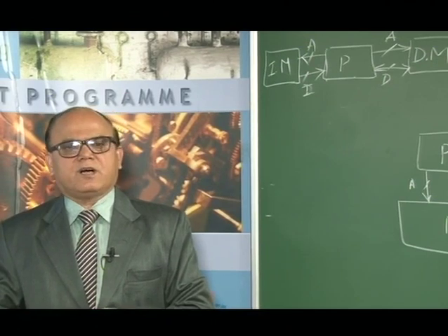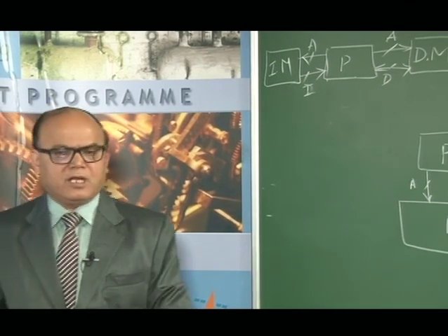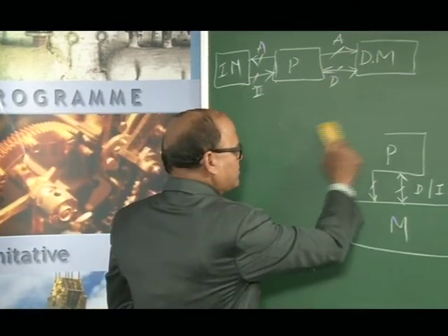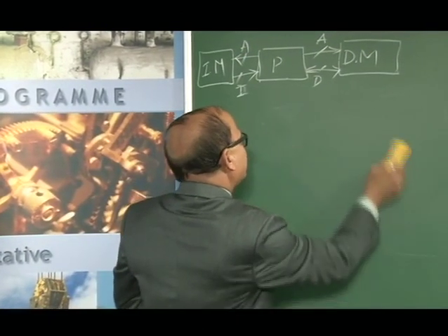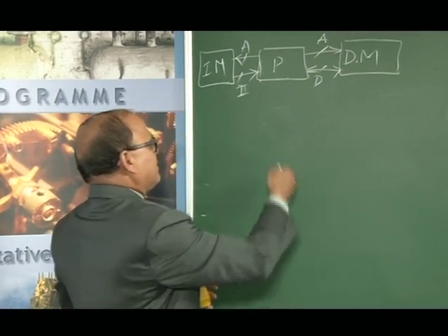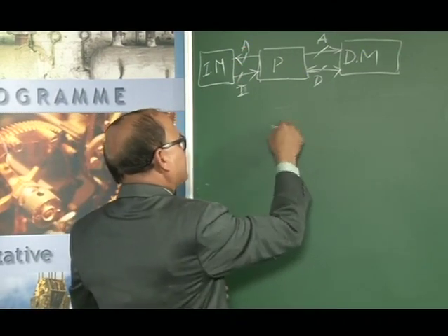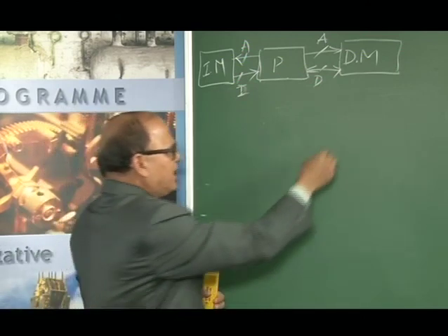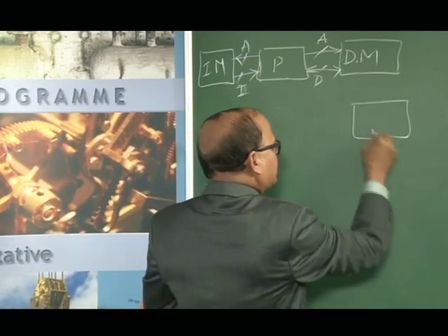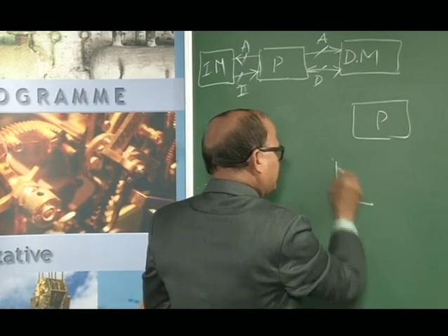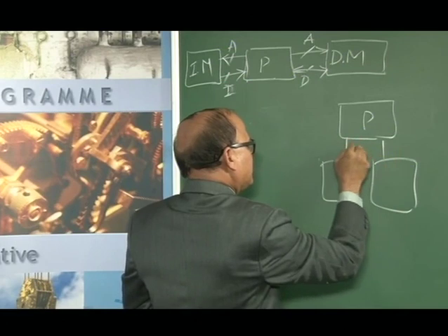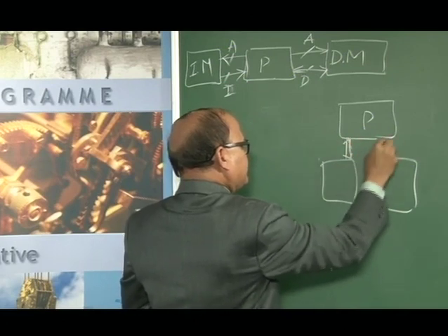So therefore the Harvard architecture always supports a higher throughput, or the overall speed of the memory access could be better. I can represent the same thing in a different way. Instead of connecting on two sides, I can simply represent the processor here, and we have separate memory units here. So this is the bus I have, right?